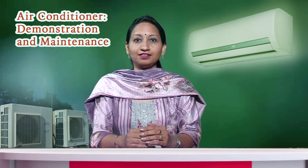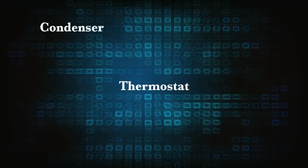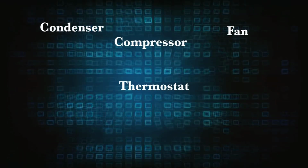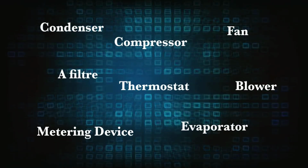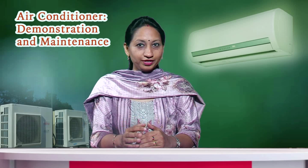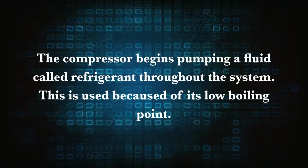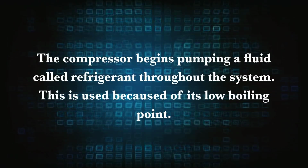As we know, there are 8 main components that play a vital role in cooling our homes. They are thermostat, condenser, compressor, fan, metering device, evaporator, blower, and filter. The first step begins with setting the thermostat to the desired temperature. This triggers the condenser fan and the compressor to run. The compressor begins pumping a fluid called refrigerant throughout the system.